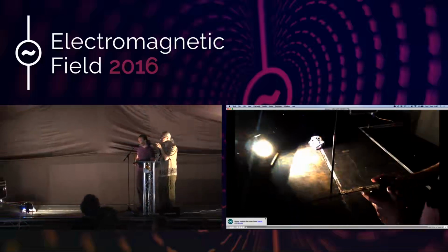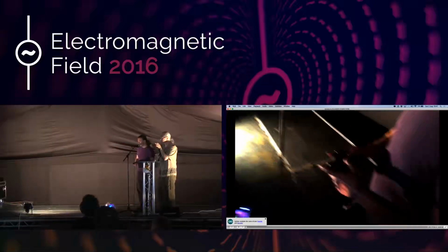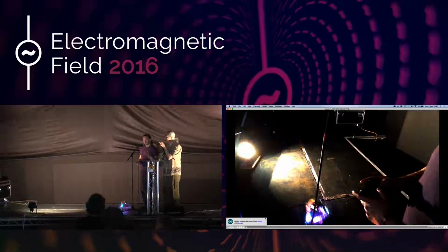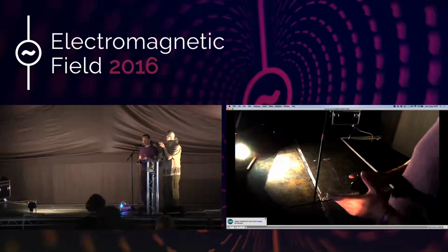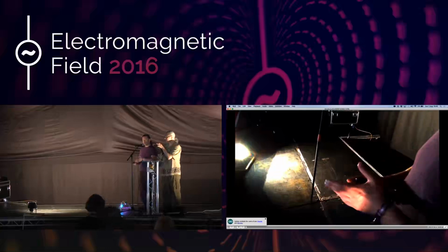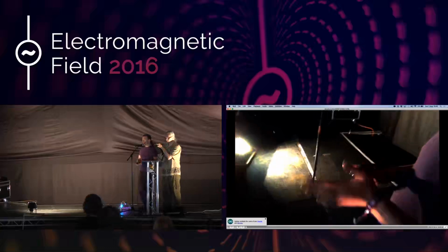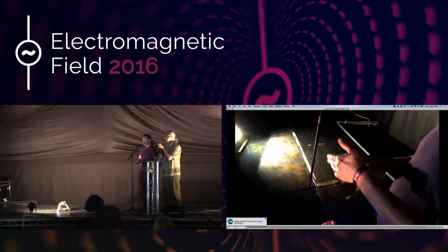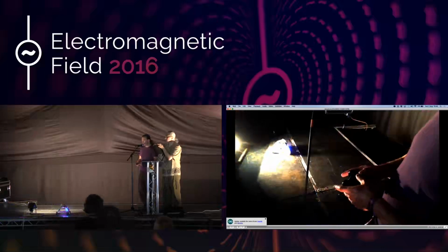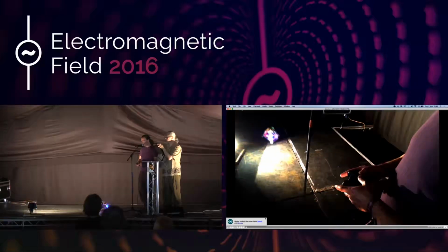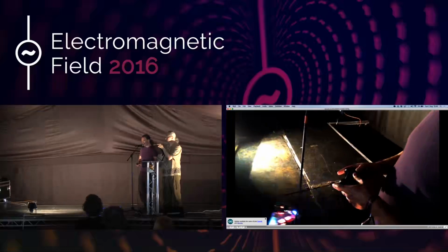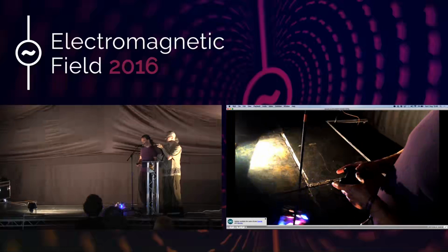But that sort of motion where we're able to move in a straight path while spinning would be almost impossible to do yourself. So what's happening there is the robot's working out what direction it's pointing. It's correcting the direction you're telling it to drive, so it's rotating it around your current pose angle, and it's sending that through. So this allows us to make motions which would be incredibly hard to actually do manually. I occasionally have to reset the spectrum. It's actually still, even after all that skidding around, forwards is still pretty much forwards on the stage. So I can reset where it thinks forwards is at any point.